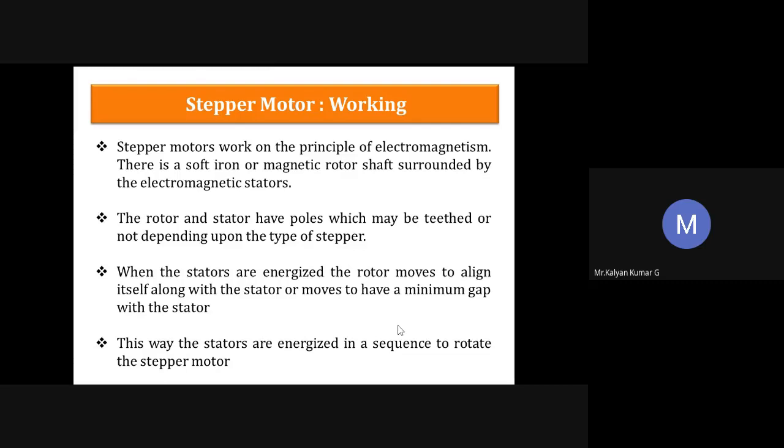And the basic step size of a motor, we call it as what? Full step. The basic step size of any stepper motor we call a full step. By altering your switching sequence, you can make the motor run with an incremental rotation of half the full step value. This is what you call a half step rotation. So we have 2 types of rotations: full step and half step.